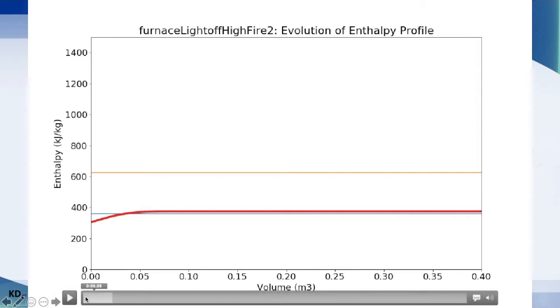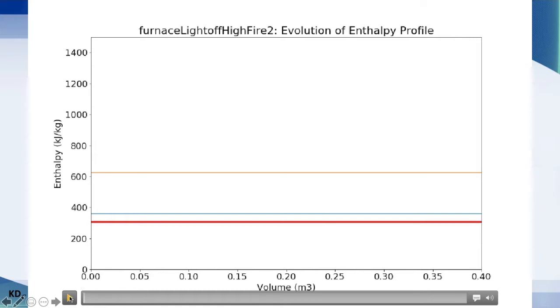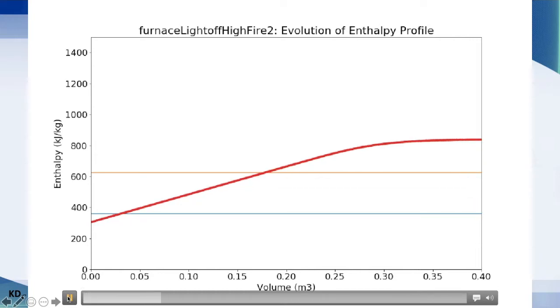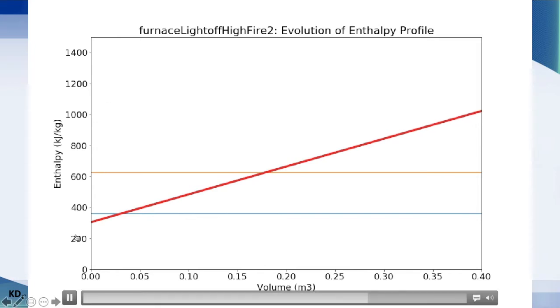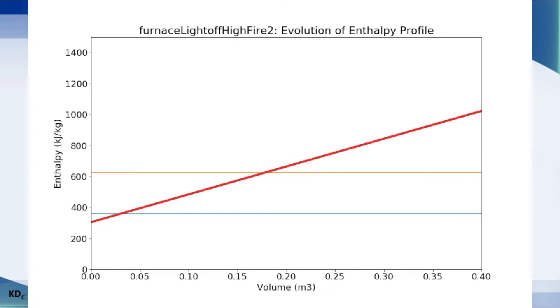So I'll just back it up and we'll see how this whole thing plays out again. This expansion pushes a 0.35 cubic meter volume of liquid propane out of the furnace tubes into the dehy vessel. The amount of vapor that we've produced increases from time 37 seconds to 50 seconds. And then after 50 seconds, we're just superheating the vapor up to 210 degrees.